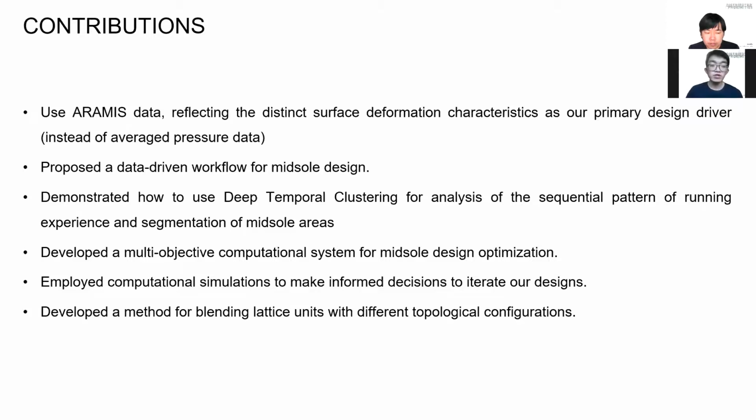We developed a multi-objective computational system for midsole design optimization, and we employed computational simulation to make informed decisions to iterate our designs. We developed a method for blending lattice units with different topological configurations.